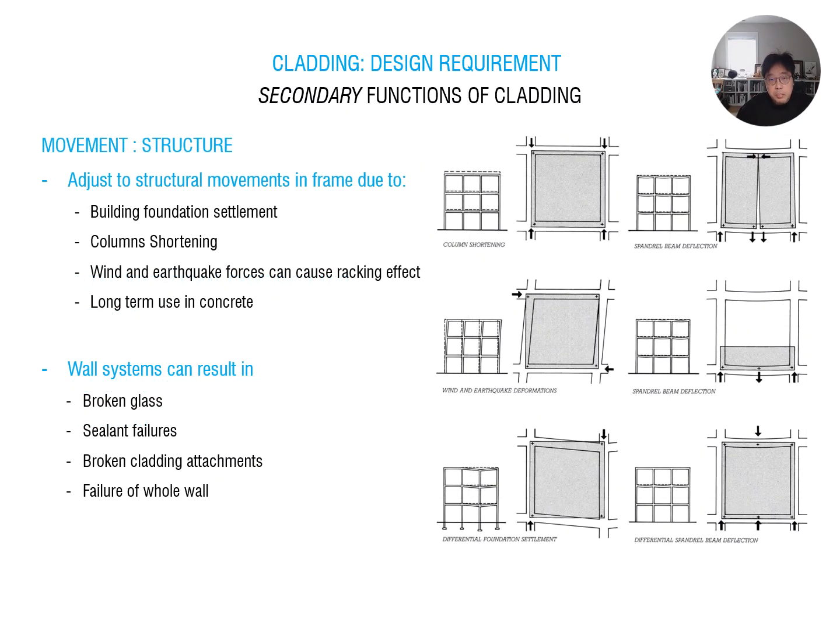So when you have this kind of movement in cladding design, you are considering structural movement. We have to consider the building foundation and column shortening, which typically occurs in high-rise buildings, and lateral forces such as wind and earthquake forces. This structural failure causes many troubles at the exterior, and you easily see cracks from it. Think about it: a building is heavy, so gravity keeps impacting it, and you see column shortening.